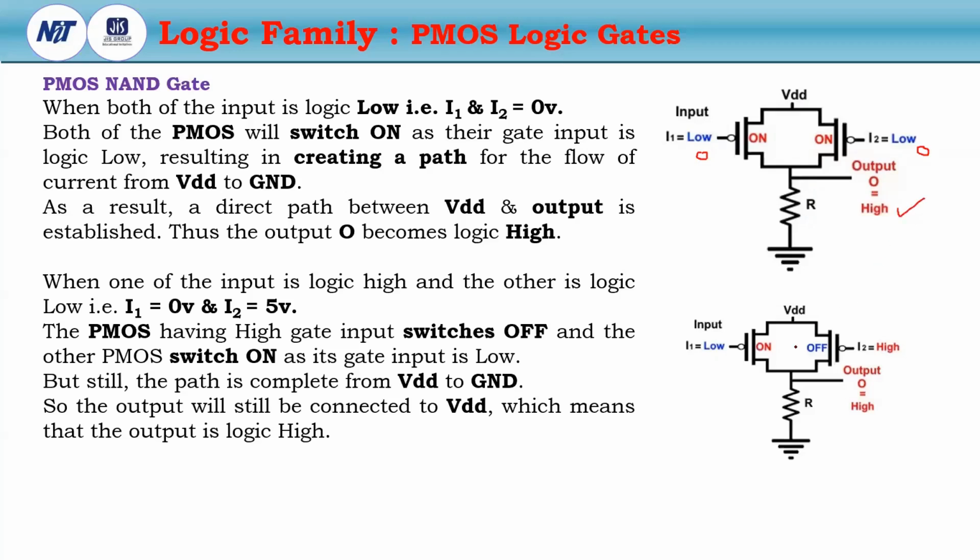Now, if any one of the transistors is turned on, the same operation is produced as before: this is off, this is on. Then due to the low internal resistance, VDD will transfer to the output and it will not go through this R due to its high value.